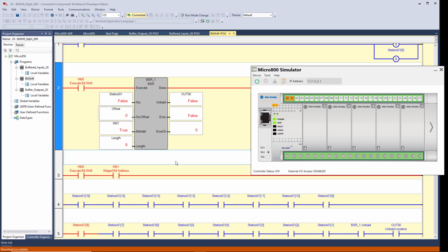You see input 0 comes on and then back off. And if you look down here, in what I'm calling the HMI, Human Machine Interface, these are just rungs with true-if-on instructions examining bits in memory so you can see what's going on instead of going to the global variables or your local variables to see if it changed state.